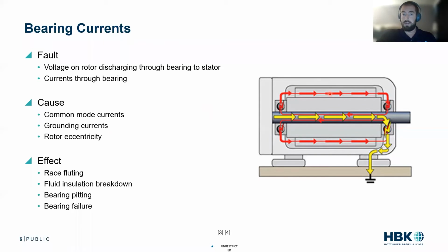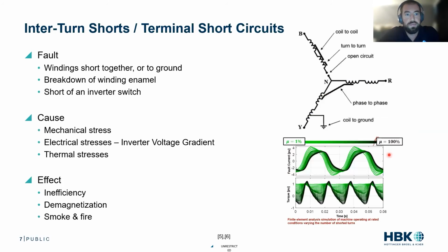And it really is from just charge getting from the stator to the rotor through stray currents, through a number of mechanisms. So bearing currents are a big one. And it is an electrical issue that results in a mechanical failure. So this is introduction one. Voltage builds up on the rotor, releases through the bearings to the stator, and it cooks the bearings. Failure mode two. And again, just giving an overview of these. We'll talk about the measurement in a moment.